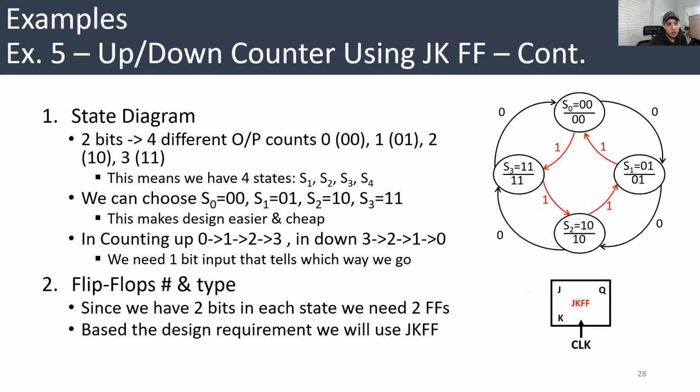In this week, we're going to continue our discussion about the design and the analysis of synchronous circuits, okay? And that's a very important topic. We're going to continue with examples and do the up-down counter again, but now using JK flip-flops. The reason is that it's trickier than using D or T flip-flops. If you do the trick in JK right, you will get the optimal design. Otherwise, your design will be correct, but it might not be optimal.